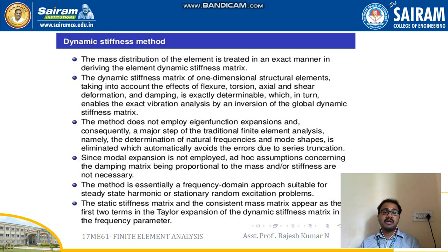Since modal expansion is not employed, assumptions concerning the damping matrix being proportional to the mass and stiffness are not necessary. The method is essentially a frequency domain approach suitable for steady state harmonic or stationary random excitation problems. The static stiffness matrix and the consistent mass matrix appear as the first two terms in the Taylor expansion of the dynamic stiffness matrix with the frequency parameter. So here we have to know the basics of the modal analysis and even the harmonic analysis for both the harmonic conditions.